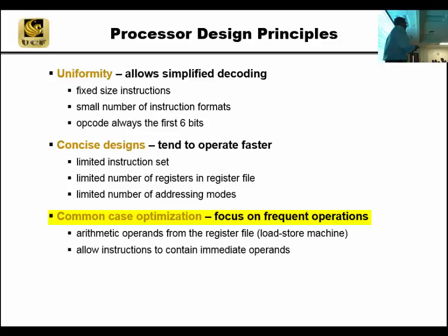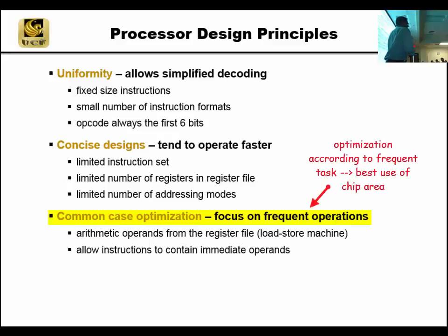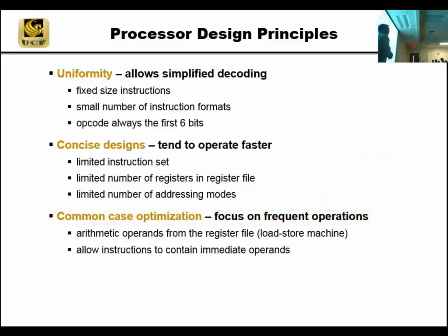From module 5, we said to make the system fast, we want to target where we're spending the most time. Every instruction has a CPI, the number of clocks. So getting the number of clocks and the percentages tells you as a designer what you want to optimize. Remember the guy running from point A to point B, who optimized the rest after getting to the start line? Here we can spend our time, energy and area on the chip to optimize where we're spending the most time for that customer.